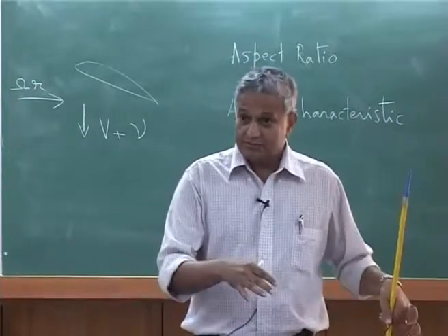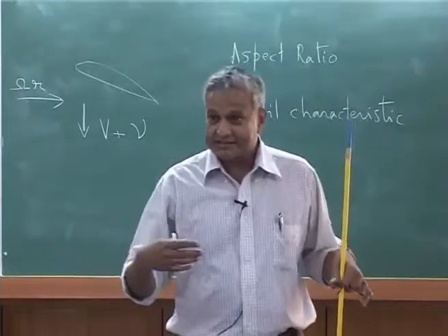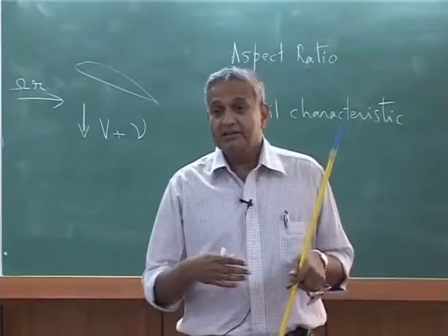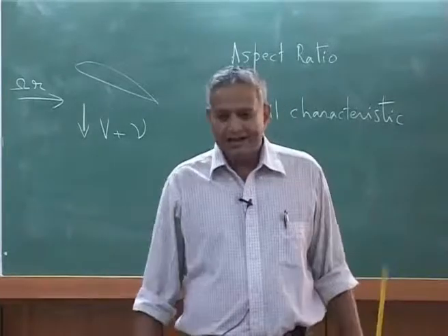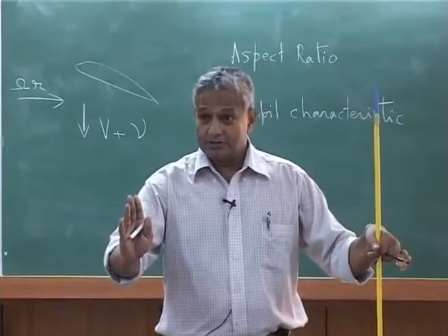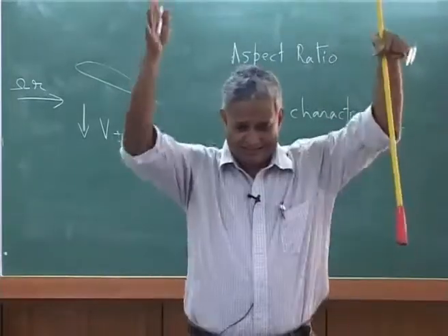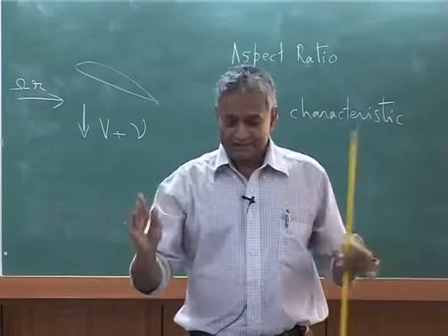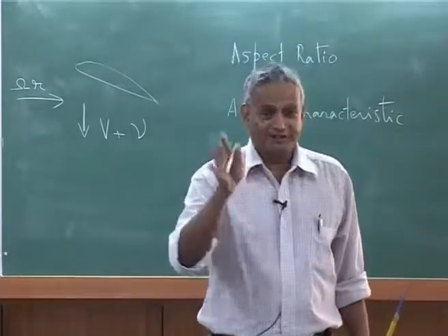Now, that you have to know, or you say if you have vortex to vortex interaction, if you consider that, then it is called the free wake theory. But if you say I fix my structure of the vortex, it is going to be in a cylindrical, vertical cylinder, that is all, no deformation, then I call it prescribed wake.